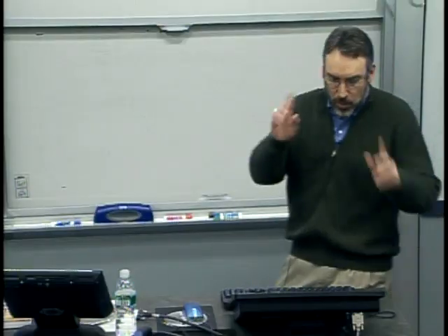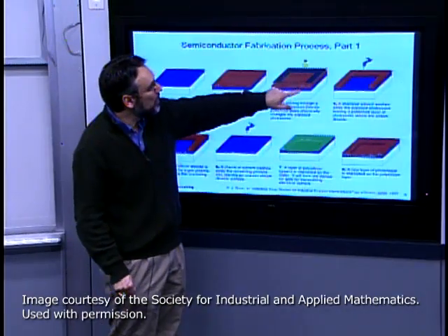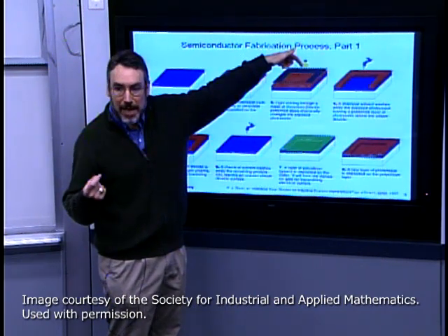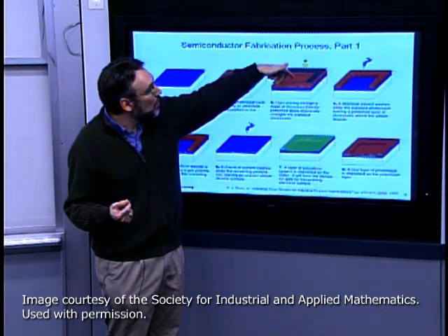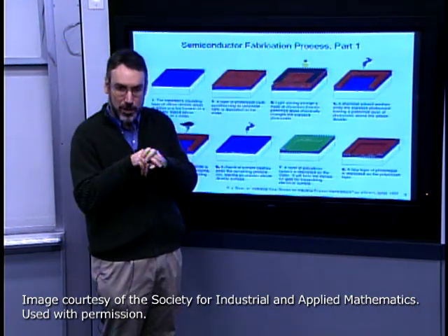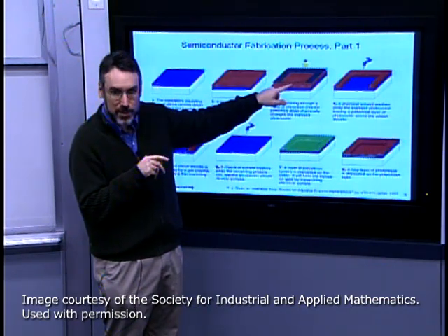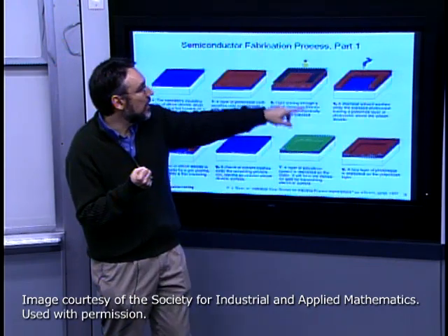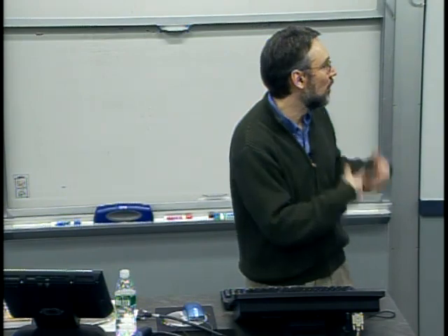No, so in this case, okay, so that's the two types of photoresist activity. So in this case, with the positive photoresist, what happens is the light energy from the exposure system will break down some of the polymer chains, these photoactive polymer chains in the photoresist, weakening them. We then go in and do a develop process where a chemical solvent is used that attacks the weakened polymer chains and rinses it away.